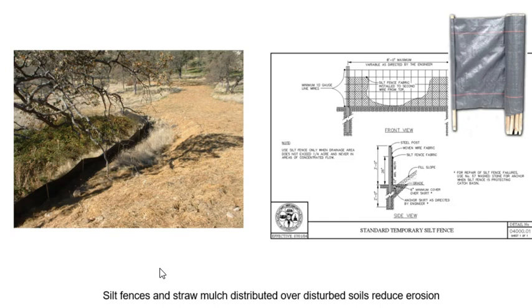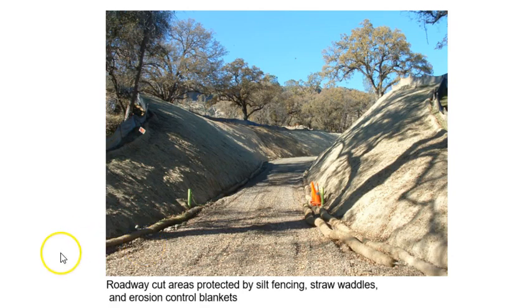So just to get a visual on what some of these are, very commonly we see silt fences. That's here. Keep the sedimentation from pushing over into adjacent properties. So the civil engineers would specify these in their drawings. There's typically at least one sheet just related to erosion and sedimentation controls, or as I said, E&S measures. So specified by the civil engineer and put in place by the earthwork contractor.